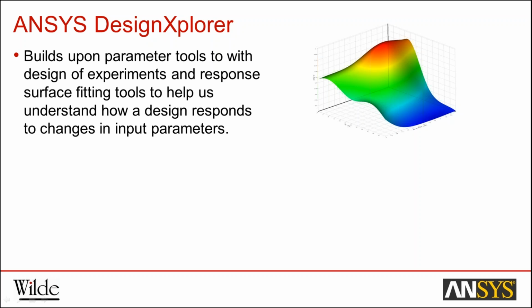Now what we can do with Design Explorer is we can ask the software to take a model and then go away and vary all input parameters up or down by say 10-20%. And then record all of the output parameters. The software will do this automatically, so it's the sort of thing you're going to set going and leave overnight. You'll come back in the morning, it would have generated a huge data set based on all the input parameters, all the output parameters.